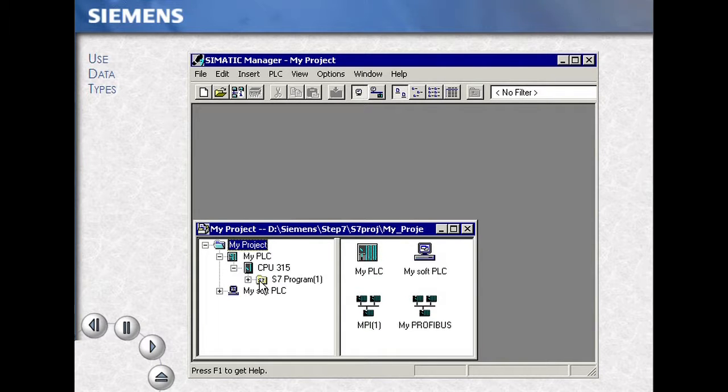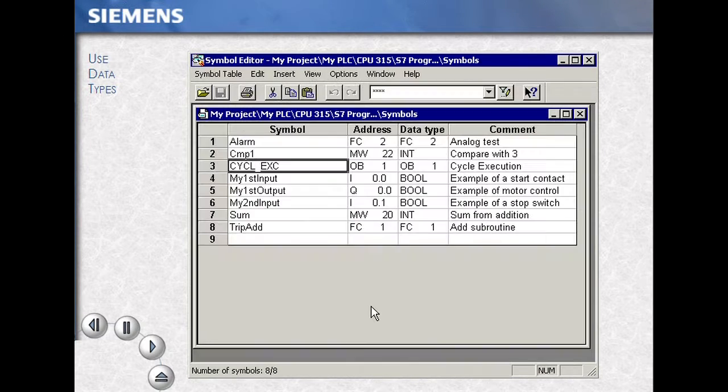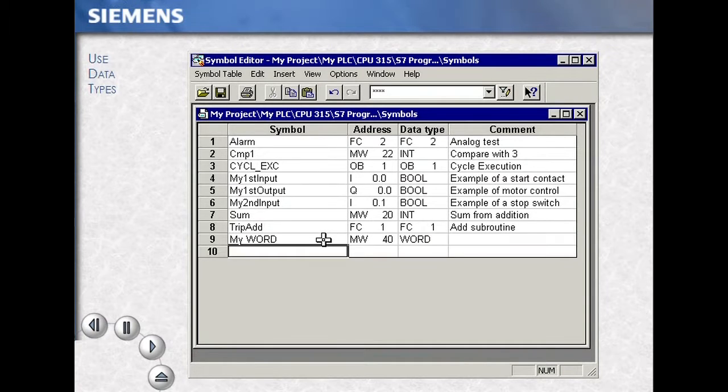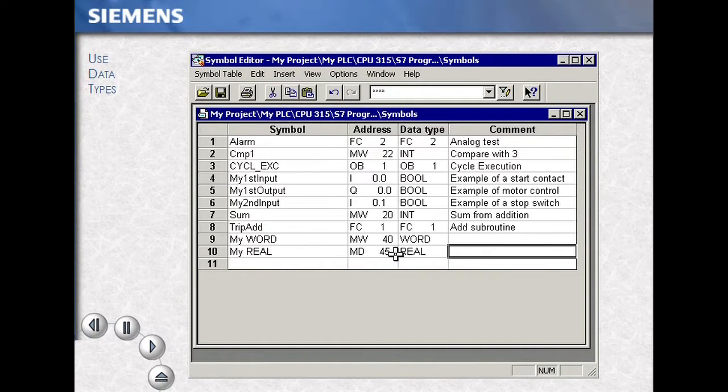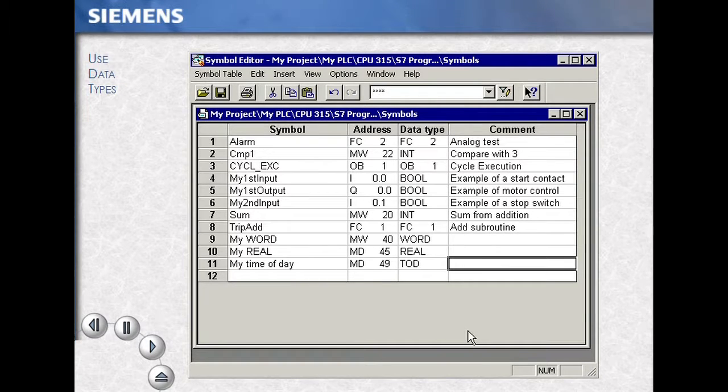This example shows several ways to use different data types. First, double-clicking in the symbol table allows us to create data type associations with process symbols, their absolute address, and their size and structure within our program. Saving your symbol table allows access to these variables by name or address later.